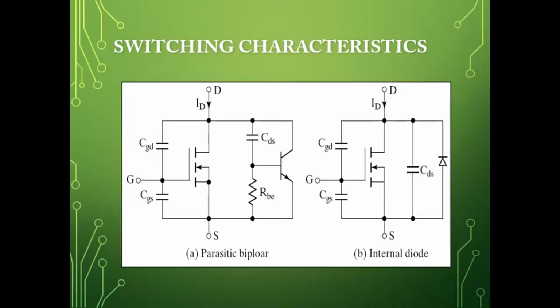it appears like this. See, if we have a MOSFET, this is a rough sketch. This is the body or the substrate. If it is an N type, it means our substrate is P, and we have drain and source. So you don't have any gate signal which is applied. Okay, the gate signal is not applied. So what is this one now? This is an NPN transistor. So we have an NPN transistor which is represented along with this resistance.